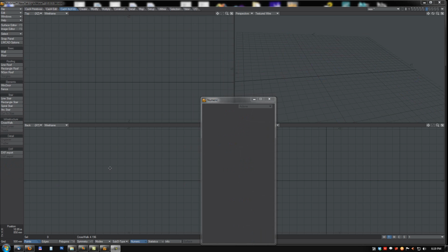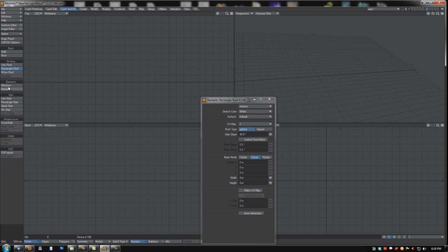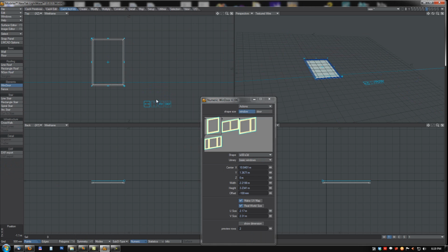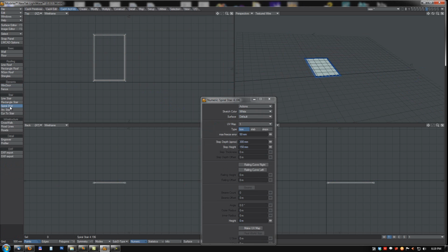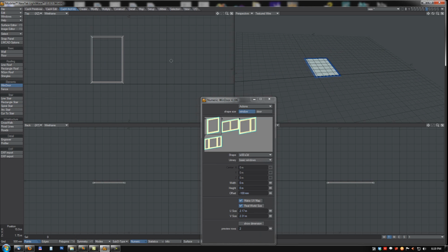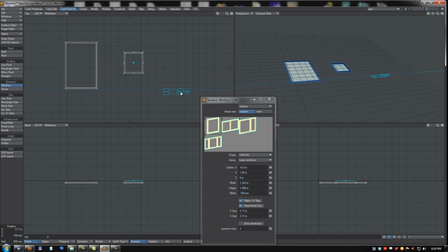Next update is with fix mode in the box, rectangle and window tool. So now when you use the window tool or box or rectangle and you enable fix mode, then even if you drop the tool and use another tool and go back to the same tool, fix mode is still enabled or disabled. And when the tool is in fixed mode and you are starting from fresh, then the dimensions of this fixed mode are loaded from the shape library from the current active preset.